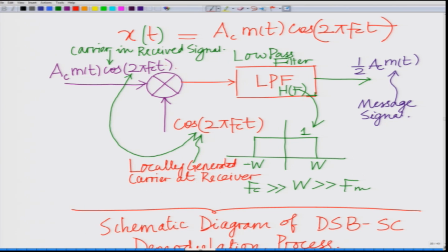However, what we have also assumed, and I have not explicitly pointed this out, is that the phase of the carrier in the incoming signal and the phase of the locally generated carrier are equal. The success of this system depends on this fact.